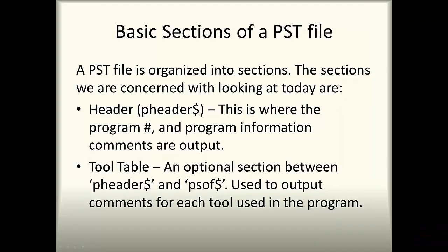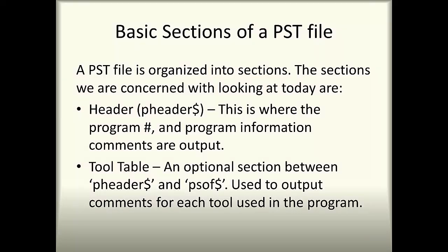So now that we've talked about control definition settings and how they can be used to input, now we're going to actually take a look at a post file. So we're going to talk about the basic sections of a post or PST file. A post is organized into sections. The sections we are concerned with looking at today are the header section, which is P header, program information, comments, or output. The tool table, this is an optional section between P header and PSOF.